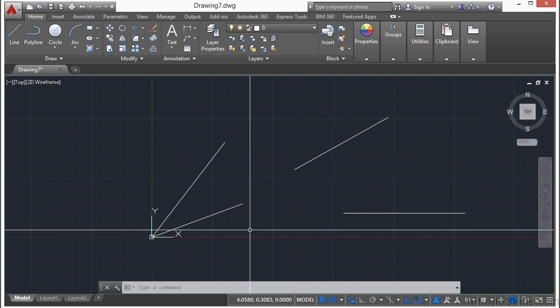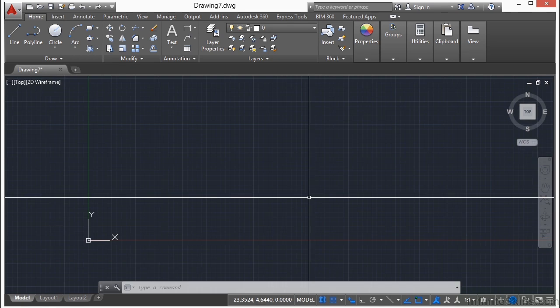When you work with the dynamic input or work with the command line, you input the coordinates in essentially the same way. By default, AutoCAD sets up the UCS in a world coordinate system. That means that the origin is at coordinates 0, 0, 0, and that angles facing east, or to the right side of your screen, start at 0 degrees.